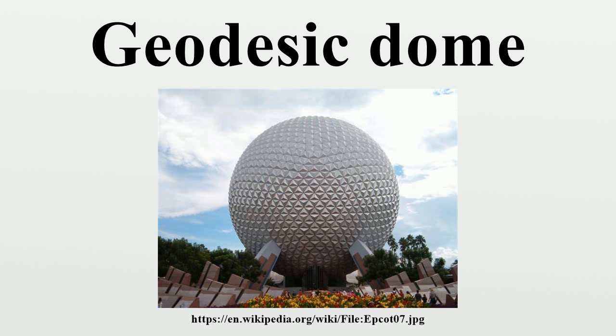This construction is well suited to domes because there is no place for water to pool on the concrete and leak through. The metal fasteners, joints, and internal steel frames remain dry, preventing frost and corrosion damage. The concrete resists sun and weathering. Some form of internal flashing or caulking must be placed over the joints to prevent drafts. The 1963 Cinerama Dome was built from precast concrete hexagons and pentagons.